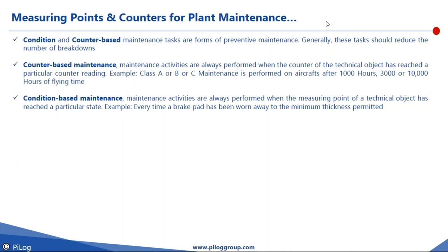So to overcome that, condition-based monitoring is the buzzword today in the maintenance era, and they talk about how I can enable the maintenance. We have talked about how there are different types of condition-based monitoring. Whether it can be counter-based, depending upon the cycles or the time of usage. That's what we talked about, an example of an airline or a jet craft's flying hours. Based on the manufacturer recommendation, OEM recommendation, they have to go for class A, class B, or class C kind of maintenance.